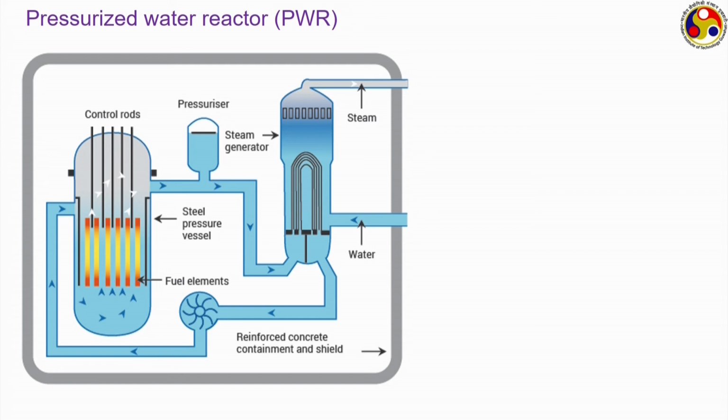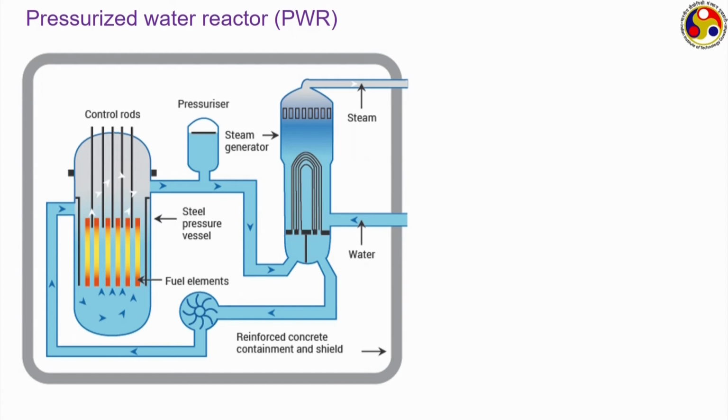It was mentioned in the previous lecture, a previous module, that in a PWR the control rods are inserted from the top, and hence the control rod connecting or driving mechanism, particularly the spider, is mounted at the top of this pressure vessel. And these fuel elements and also the control rods are completely immersed in the moderator, and the moderator in this case is water, that is, only liquid water. No phase change is allowed in a pressurized water reactor, and the water that we are using as coolant and moderator must remain as single phase liquid in order to operate a pressurized water reactor.